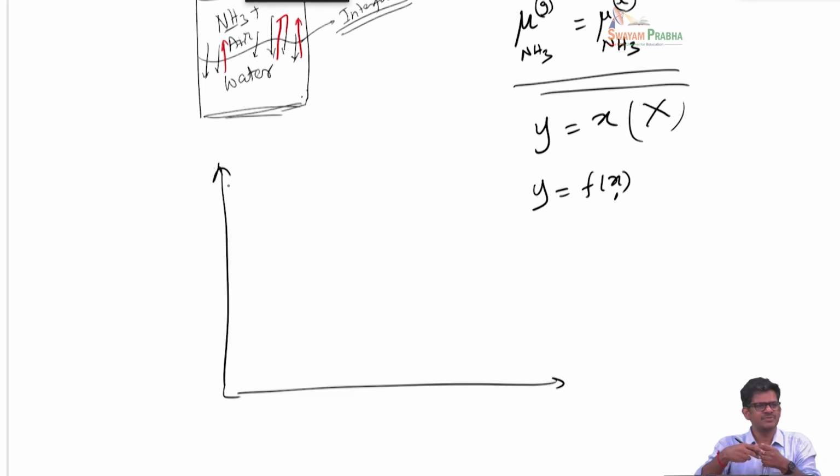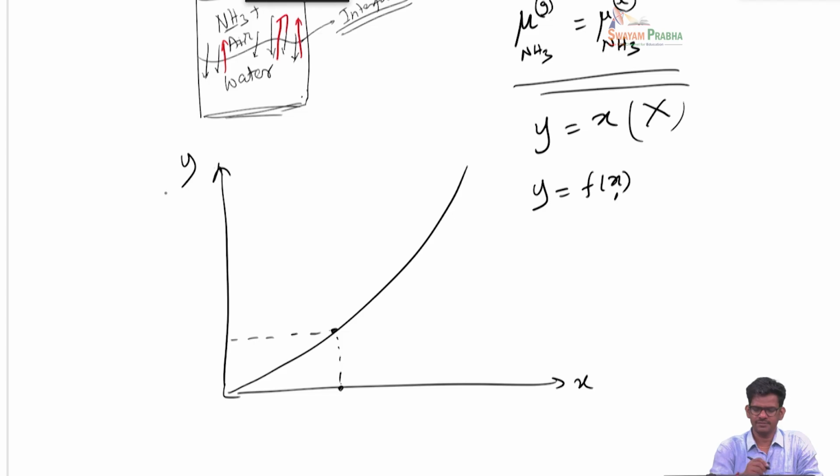So if you imagine you have done this experiment, by injecting it multiple times, you can actually have a nice functional relationship between the equilibrium composition in the gas phase versus the equilibrium composition in the X phase, or the liquid phase. So, this may be the one corresponding to the initial times, and you add a little bit more ammonia. Then you would have reached somewhere here, the new equilibrium state, and if you continue this experiment further and further, then you get this equilibrium curve. So, this is what we call an equilibrium curve.